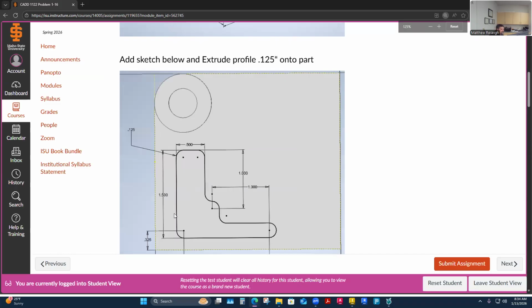Like when I look at this, I'm like, well, how do I want to draw this? I don't know. A lot of times I will draw these as sharp corners and then use fillets. That can run into a problem if you have fillets running into fillets, and then there might be a line segment that gets stuck in there, and so your sketch geometry gets really little pieces.